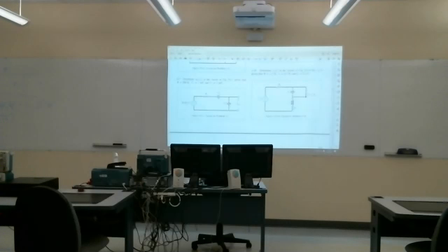What would the inverse Laplace transform of that be? So this is capital H, and the little h is what we call the impulse response. If you remember this from your Laplace transform table, this would be e to the minus 6t u of t, the impulse response. Is it a stable system? Where's the pole of the transfer function? At -6.